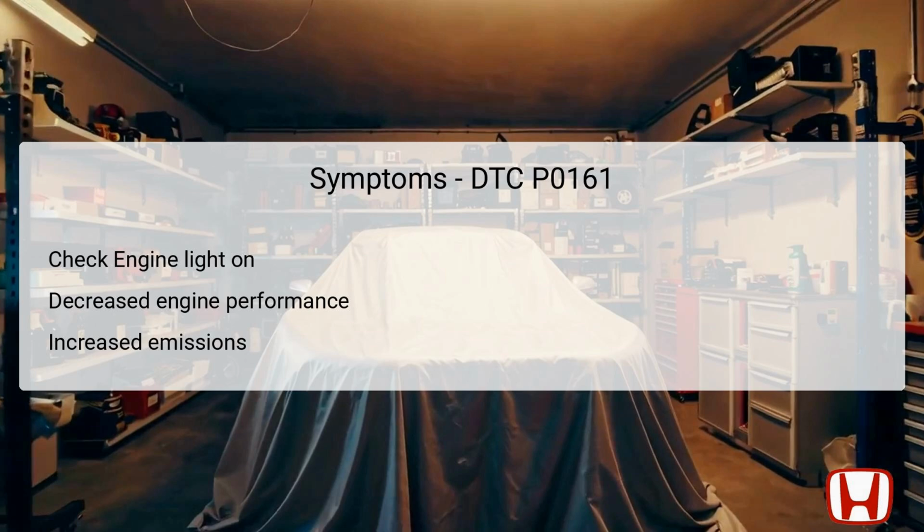Drivers may also notice a decrease in engine performance, including issues like rough idling, reduced power, or hesitation during acceleration, as the oxygen sensor provides inaccurate data to the PCM. Increased exhaust emissions may result as well, potentially leading the vehicle to fail emission tests. These symptoms underscore the importance of promptly addressing any DTCs, as they can have significant implications for both vehicle performance